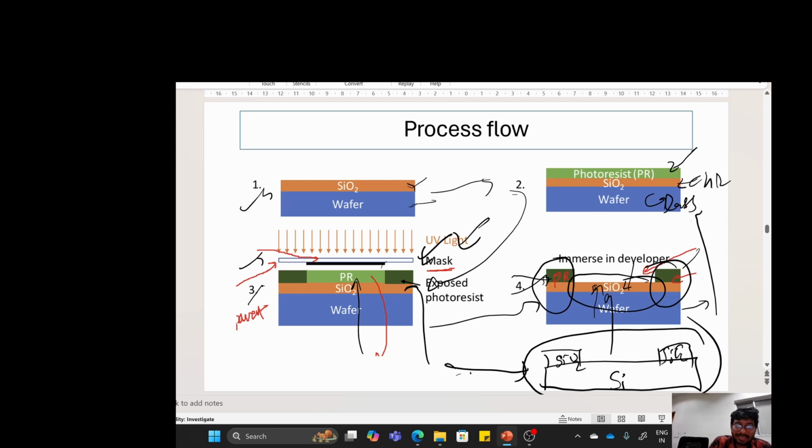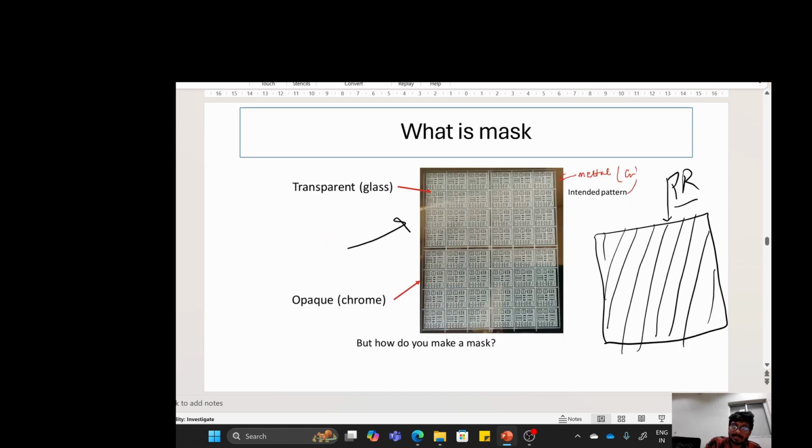But instead of light through a mask, we use a laser. In that case you don't require a mask, and the laser writes like a pen, pixel by pixel, over this mask. We first remove the exposed area of the photoresist, and then the chrome under it gets exposed where we shone the laser light.